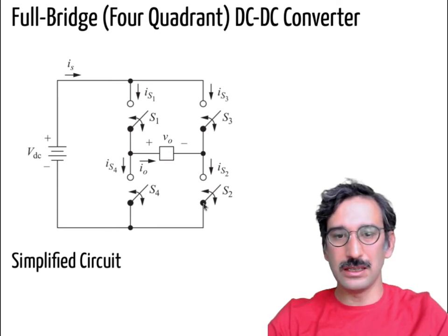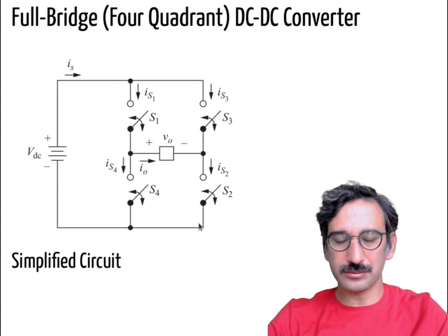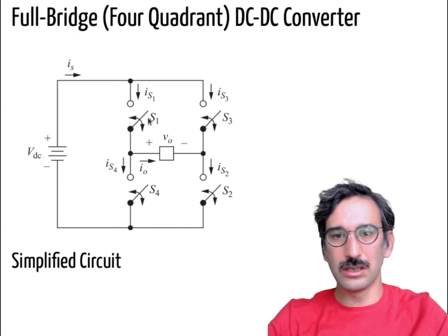If you have that kind of converter, you can close S1 and S2 if they are on. You see VD on that side, while the current is flowing in that direction, and you have the anti-parallel diode, so you can still have negative current.